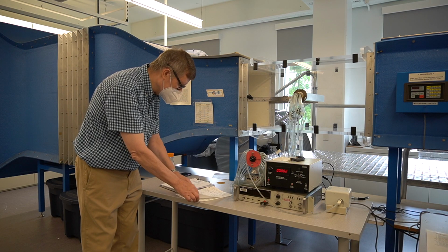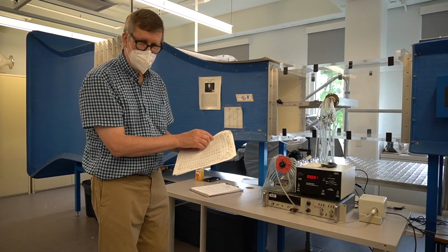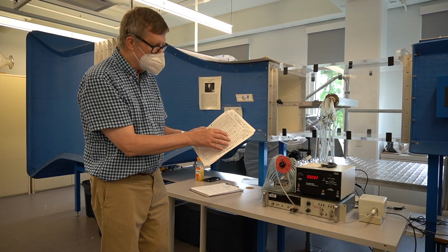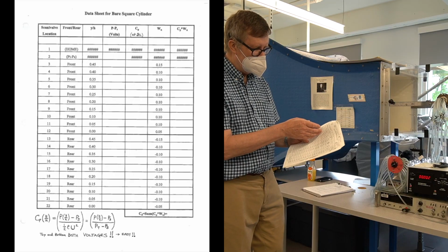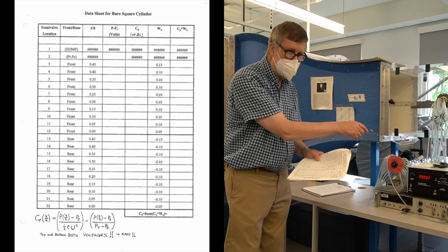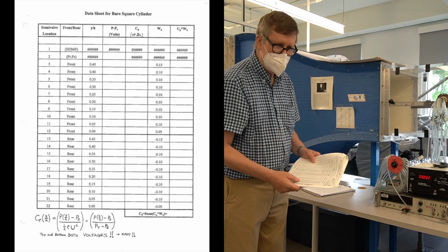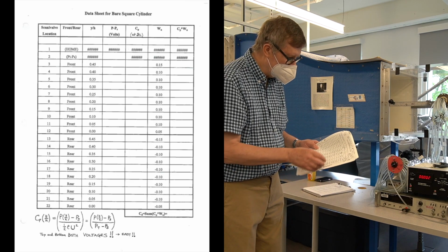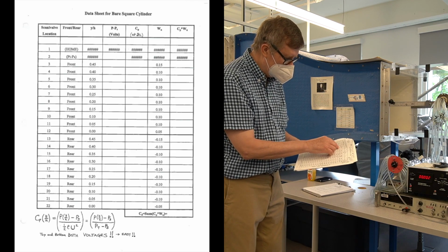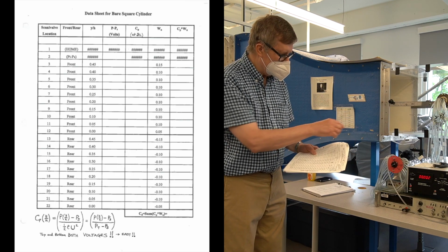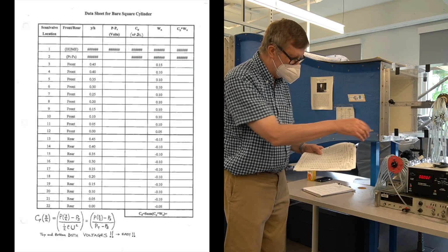And in our table, can you turn over the page? Nice. Okay, so on this table, which looks a lot better than the one I've got here, the first column is scanning valve location, telling you which pressure tap you're actually measuring. Then you enter into this column the actual measurements that you get off the anemometer and the transducer.